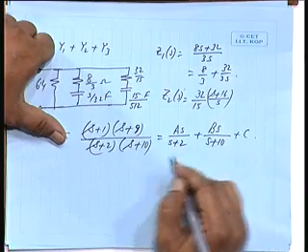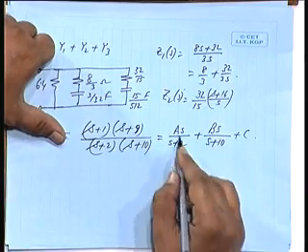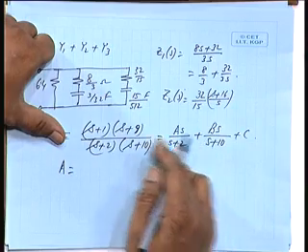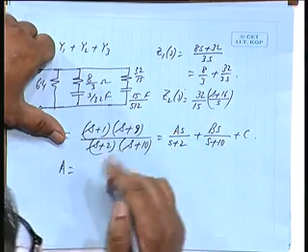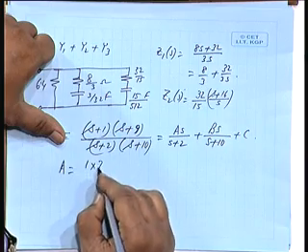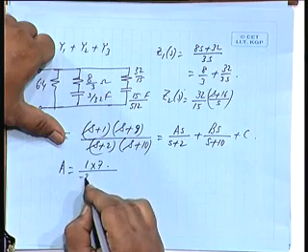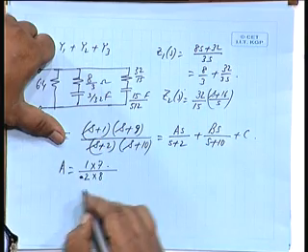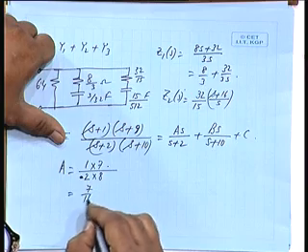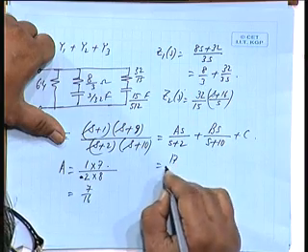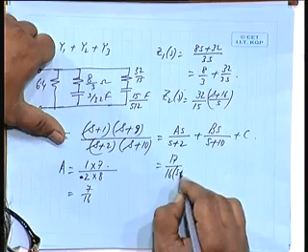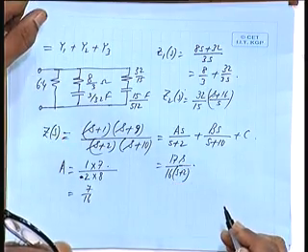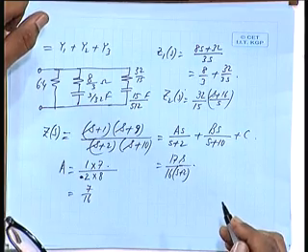Okay. Let us calculate just one of them. What is the value of A? If I multiply by s plus 2, divide by s, make s plus 2 equal to 0, it will be 1 into 7 divided by minus 2. Okay, I will not put minus 2 because minus 1 is also there. 2 into 8. So, 7 by 16. So, this will be 7 by 16 into s plus 2 into s. This is an admittance function, is it not, for an RC network.